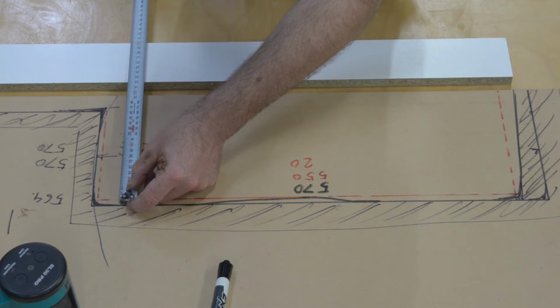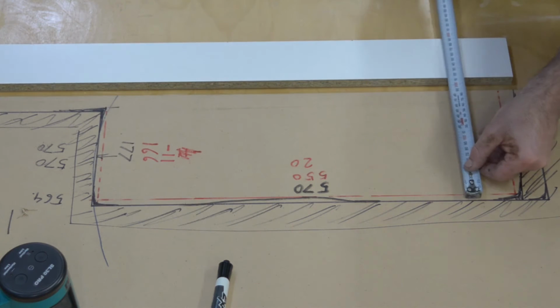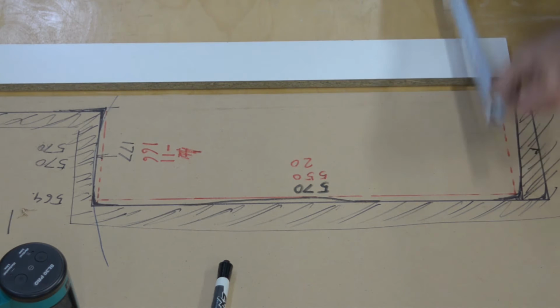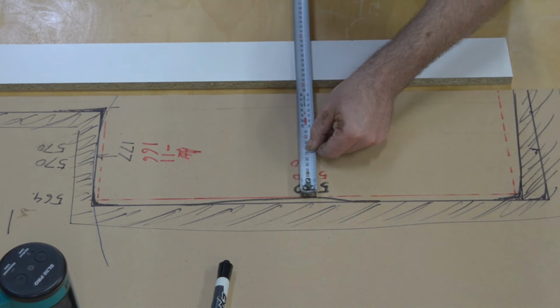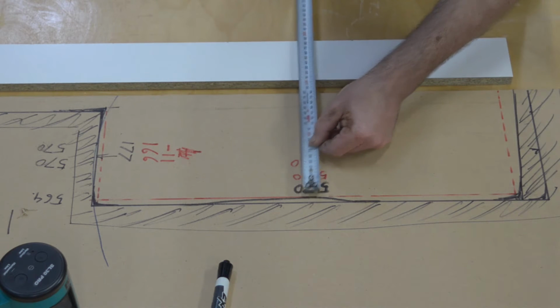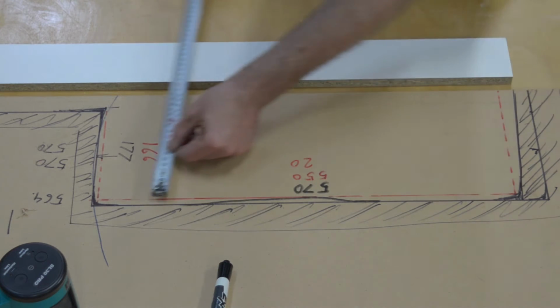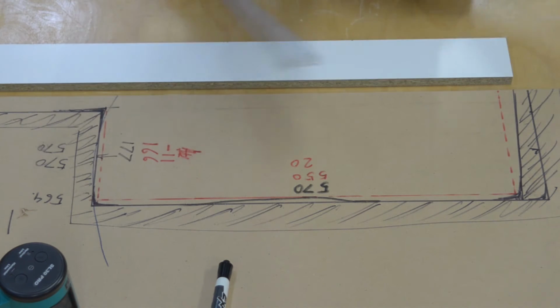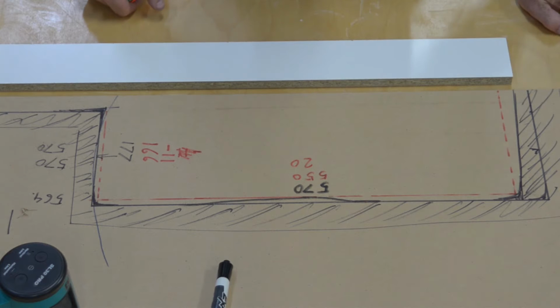So I'll make this side 220, and that side also is now 220. So I could go along and look for any bumps. So that's 210. That's telling me already, comparing to my plank, that we've got a 10 millimetre variation. And my temptation is to throw another 5 millimetres in there just as a tolerance, because there'll be other variations.